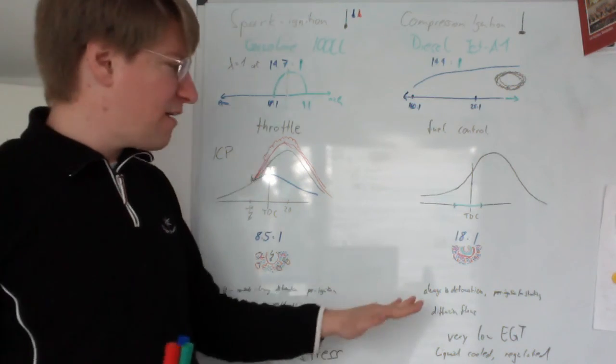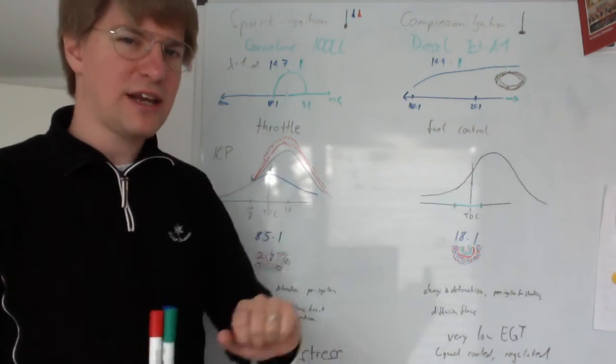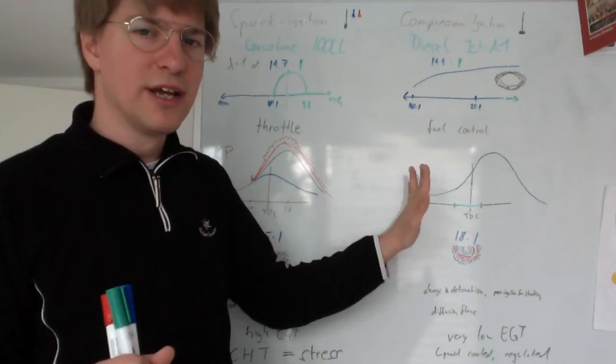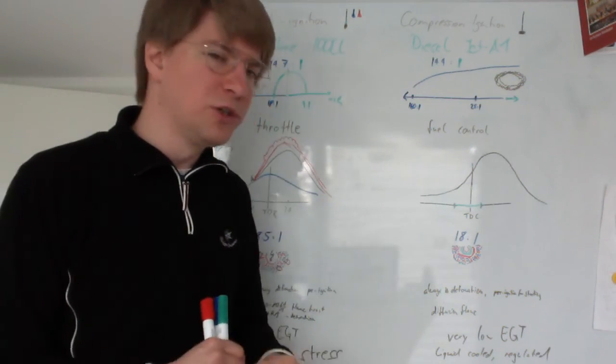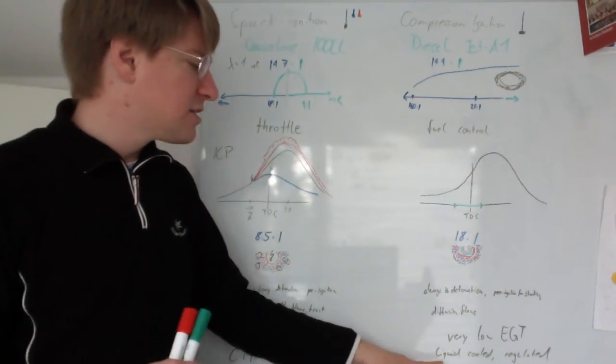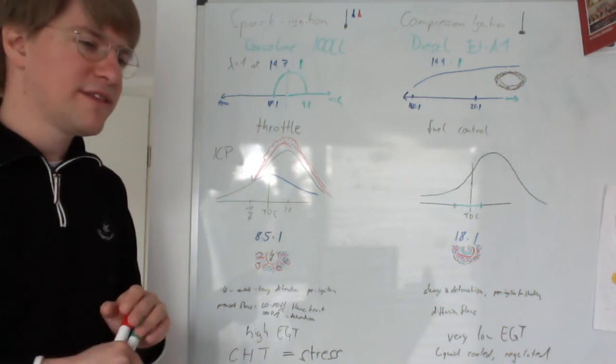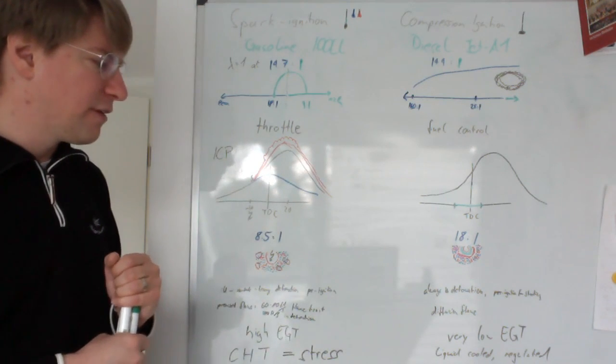And we also have less problem with cylinder head temperatures, because the diesel engines in airplanes are all liquid cooled. They have a thermostat, so we can control the temperature of the engine very precisely.